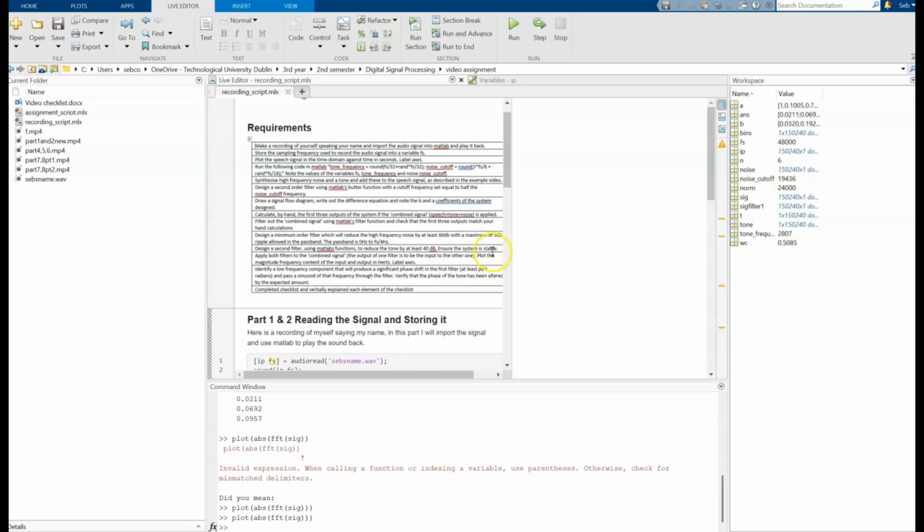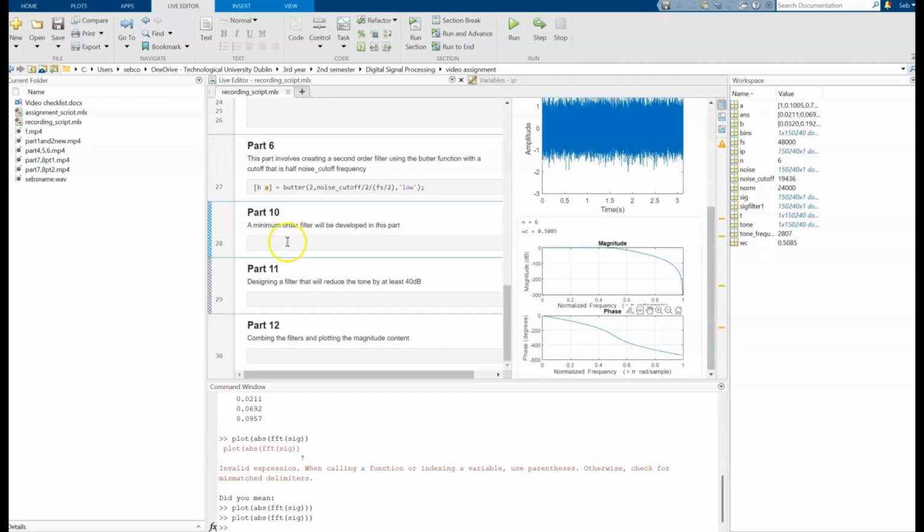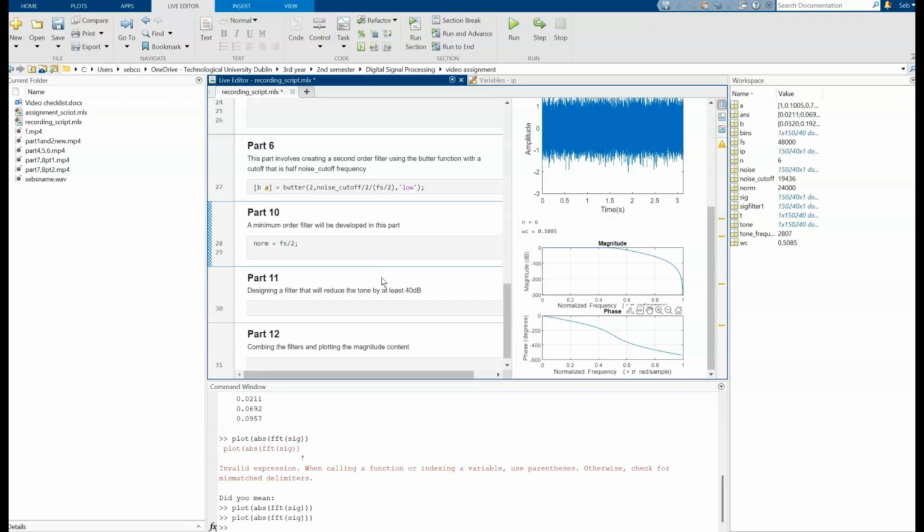And then we want a 3 dB passband ripple and the passband from 0 Hz to fs over 4. Okay, so just to start off, I want to define the norm equals fs over 2 instead of drawing fs over 2 every time. Then I'm going to use the buttord function. So the buttord function takes 2 outputs, n and omega c. So n is the order that this function will recommend, and omega c is the cutoff frequency. These are both outputs of this buttord function.